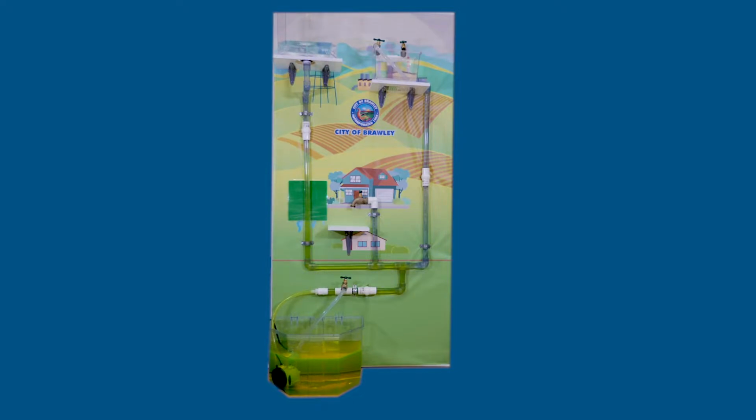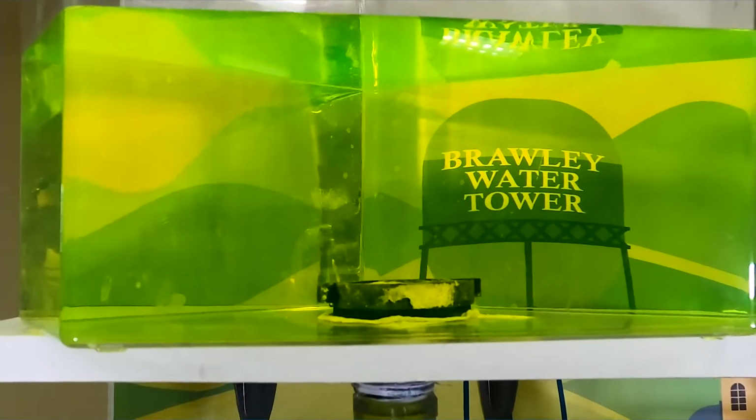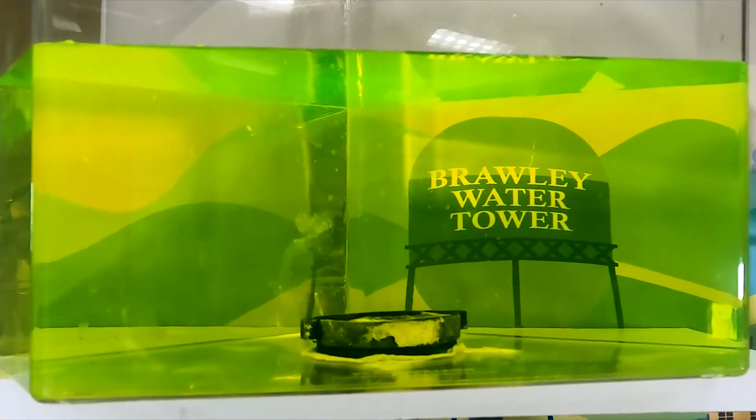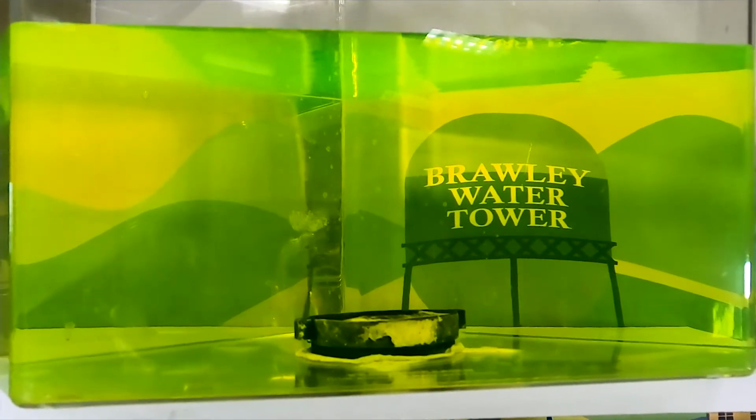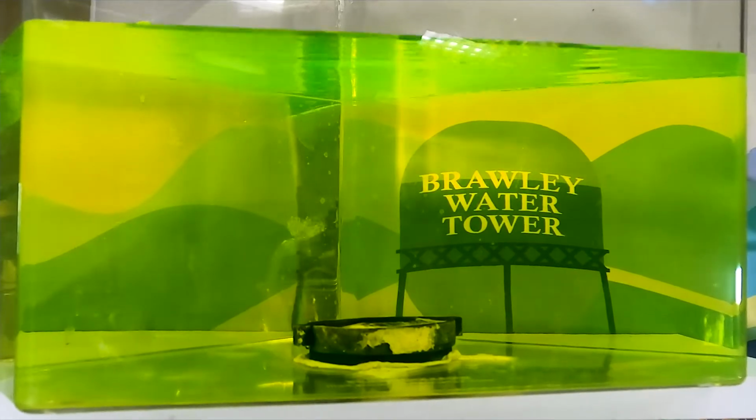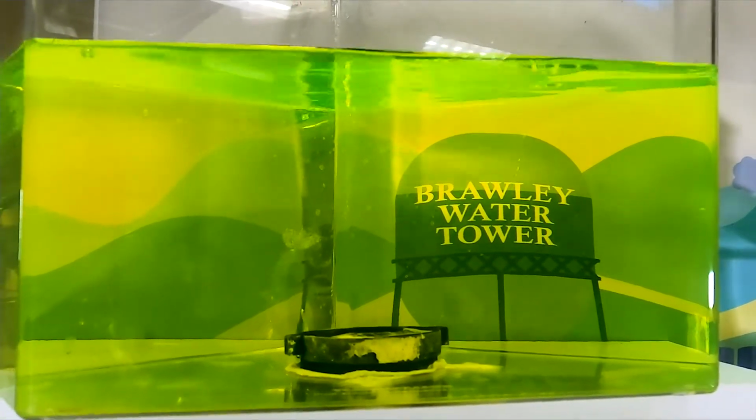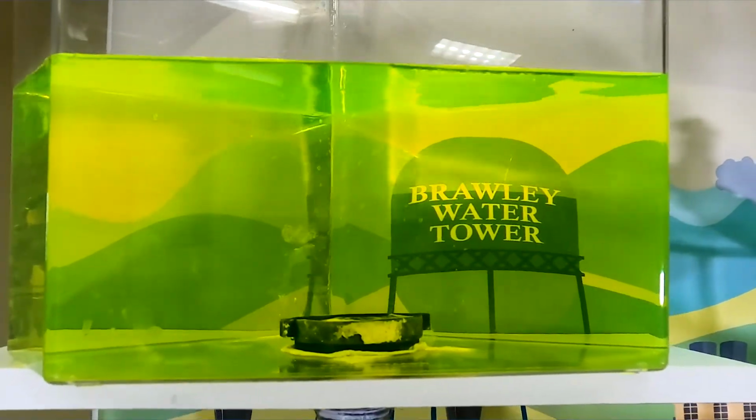In the city's water treatment plant control room, alarms are going off, and the SCADA system is showing that the tower has started to fill without any work being carried out by the city operators. The on-site operator goes and starts taking samples from the water tower, where they immediately notice something is wrong. The water has a green color and fails on water quality checks for chlorine. They then isolate the water tower supply and escalate their concerns to the water treatment plant chief operator.